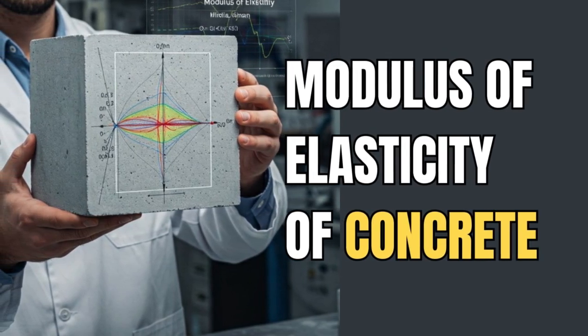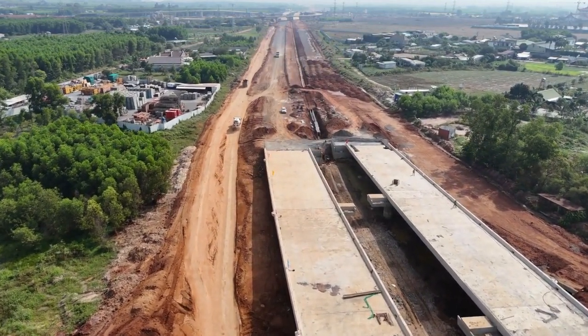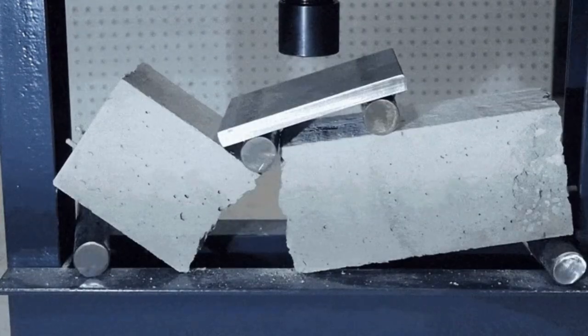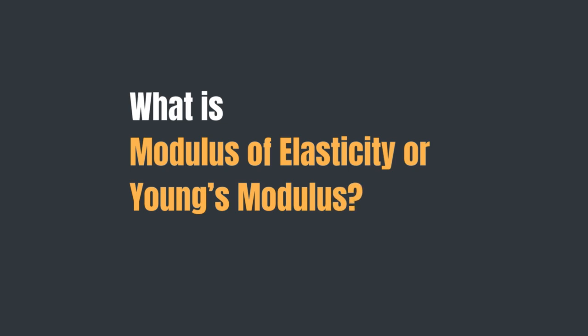Modulus of elasticity, or elastic modulus, is a key parameter when designing concrete structures. This value tells us how a material will behave under stress, giving us an idea of its stiffness. And it's actually a good indicator of the material's strength too. Now, to truly understand what modulus of elasticity is, we need to look at how it's derived.